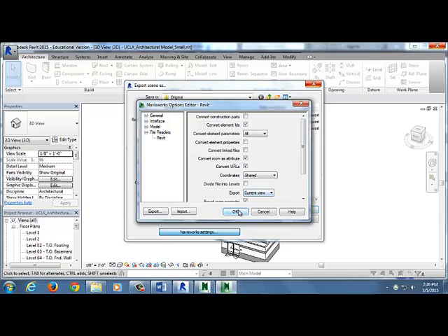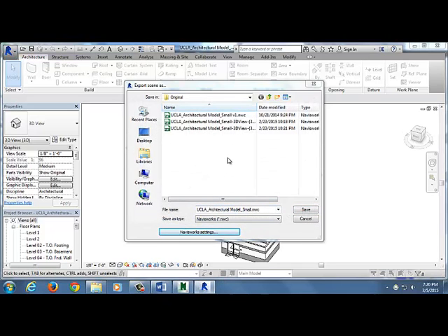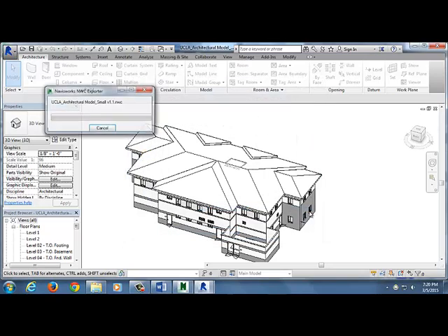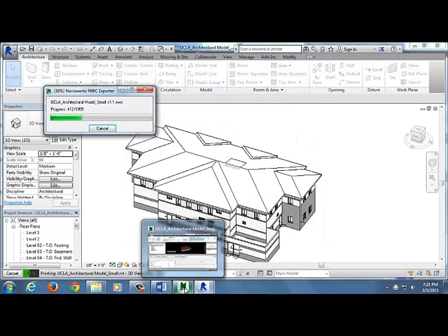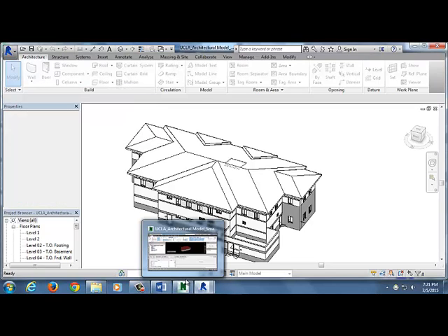Let's do my current view, and I'm going to call it my V1.1. Because then I feel like I don't have to use my search sets as often. I like to keep it clean and work through the model tree, the selection tree, when I do my takeoff.